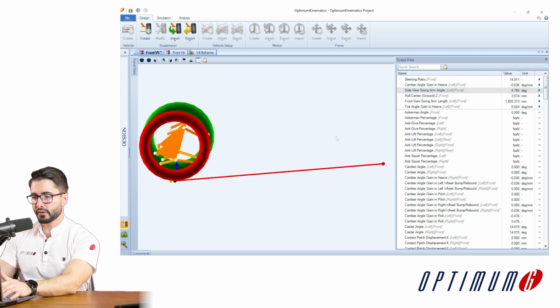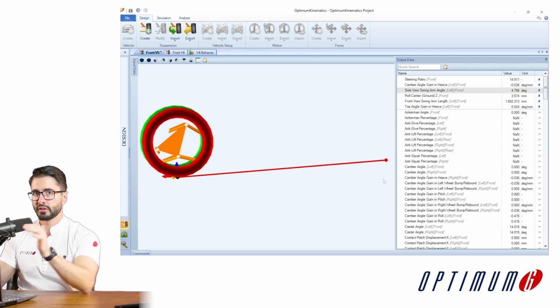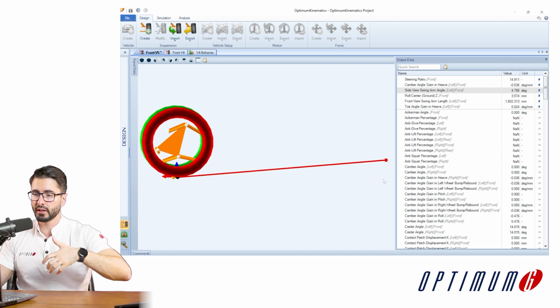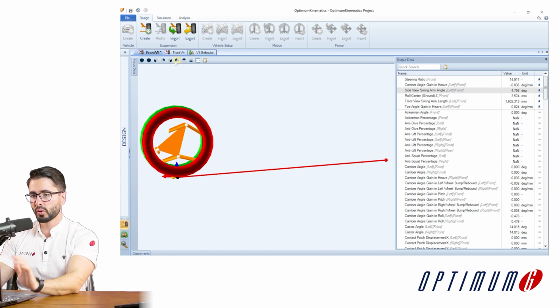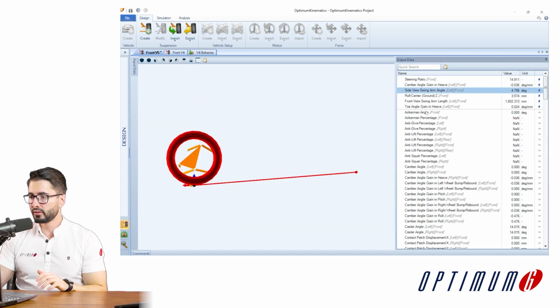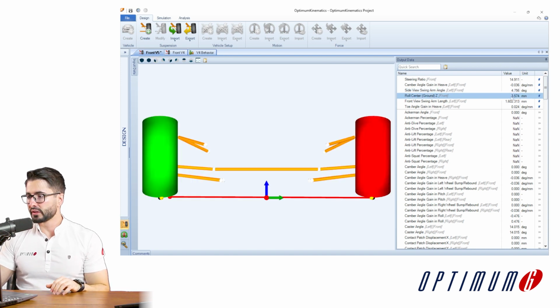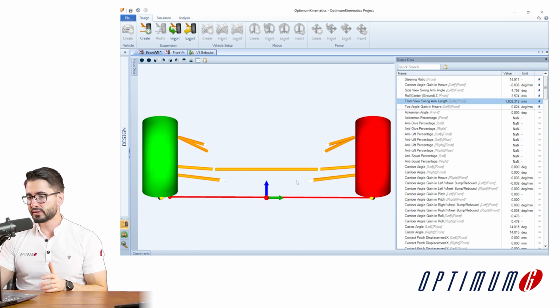Of course, these are changing many other things, such as the longitudinal distance and the height. And this will influence parameters such as caster variation when you are braking, or wheelbase variation as the car moves up and down. But we're not too worried about that in this exercise. Once we've fixed the angle, we should go back to the front view and reanalyze the parameters. We can see that the roll center was heavily influenced by that change. It went from 20 millimeters to 3, as well as the lateral distance of the instant center. It went from 1.5 to 1.6.